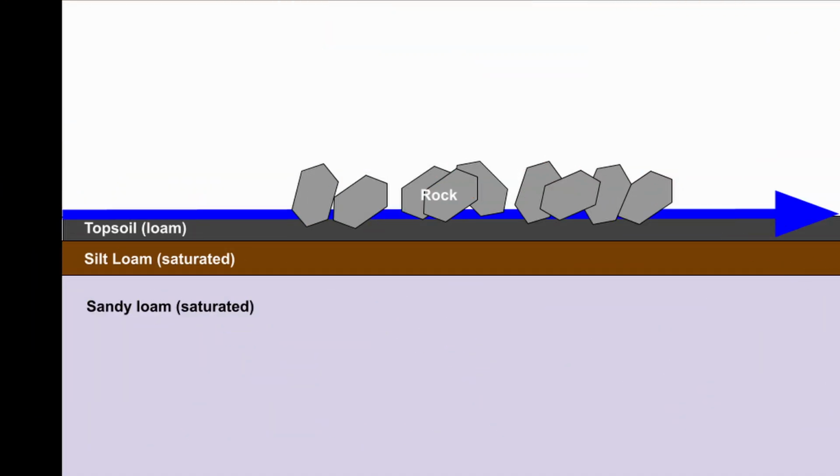This drawing shows what not to do when using rock to armor a spillway. The rock was placed on the surface in a thin layer and it was not embedded in the ground. The rock will be washed downstream when it rains. There are wide spaces between the rocks. Water flowing in this spillway will flow around the rocks and it will cause erosion.